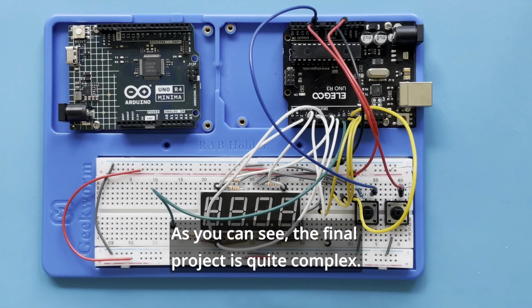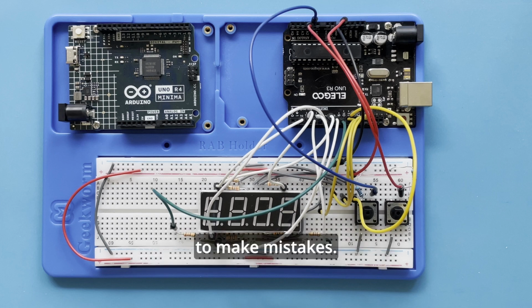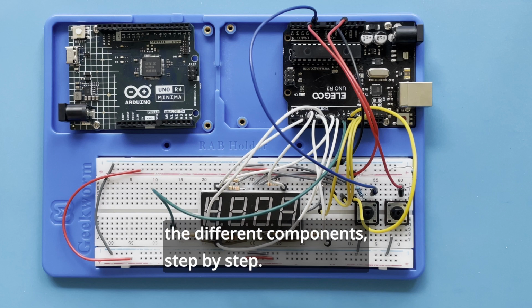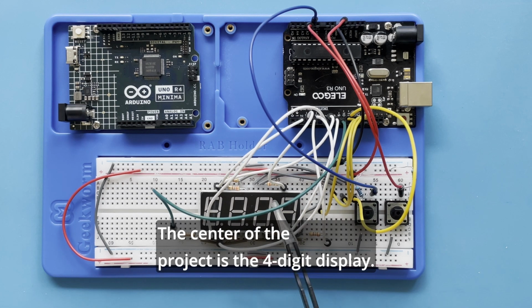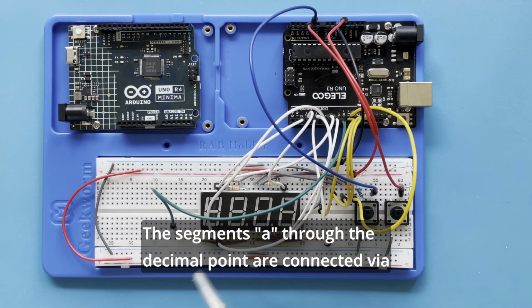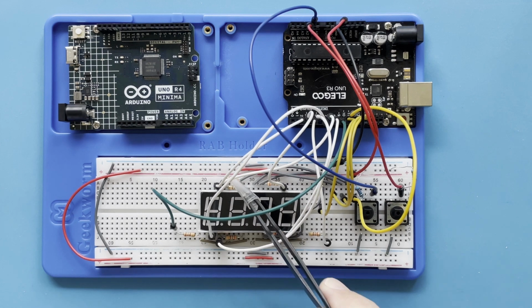As you can see, the final project is quite complex, which means that your students have plenty of opportunity to make mistakes. In order to speed up the video, we will go over the different components step by step. The center of the project is the 4-digit display. The segments A through the decimal point are connected via 220 ohm resistors to the digital pins 3 through 9.